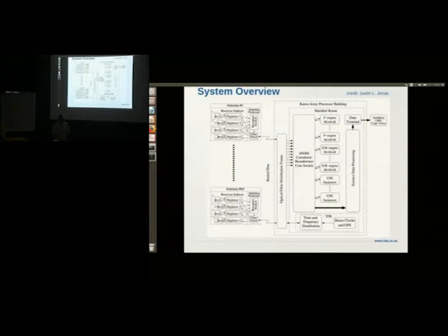So this block diagram gives an architectural overview of the telescope. You've got 64 inputs, and you can select. So this is on one antenna. So you've got the receivers, and you've got the digitizers, and you can select either UHF, L, or S-band. After it's being digitized, it gets converted into an optical signal, also in the digitizer units, and that goes to the receptor switch.